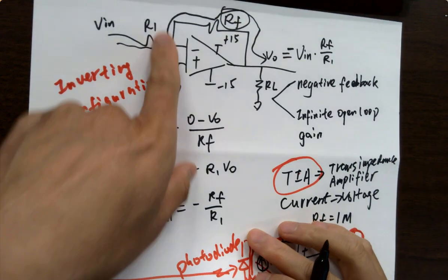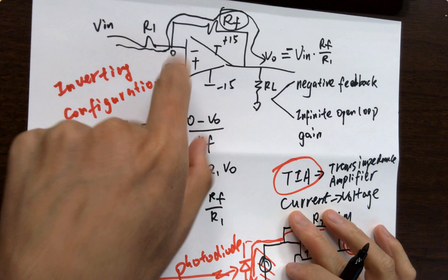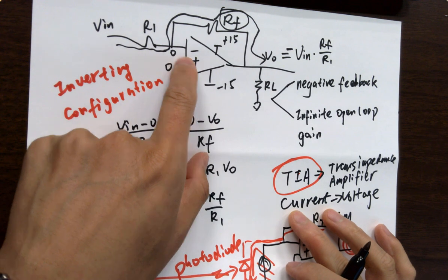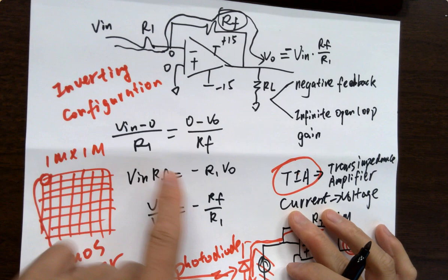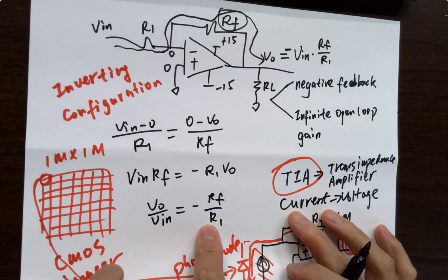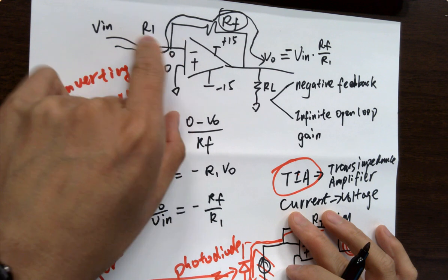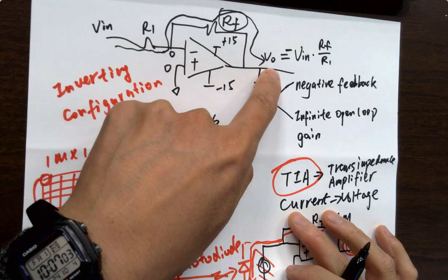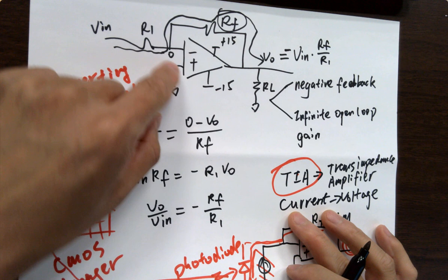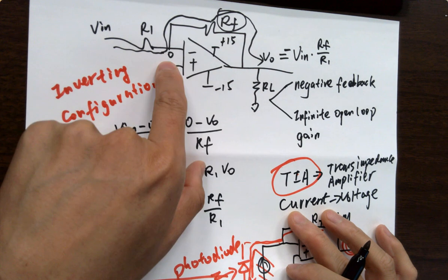So now, what you need to know is if this is given to you, can you calculate the voltage gain? It's just basically using Ohm's law, get current flowing through it. So the thing we need to remember now is these are equal if this is a negative feedback.